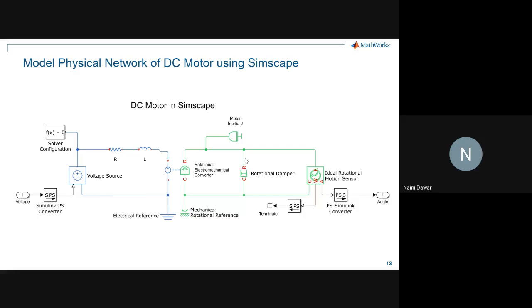So it entirely depends upon your area of application, and at times upon the fidelity of your model. If you have a linear model and you don't want to get into the dynamic or switching behavior, you might prefer just Simulink. But for a higher fidelity model, or if switching characteristics are to be involved, your preference for the modeling approach will change.